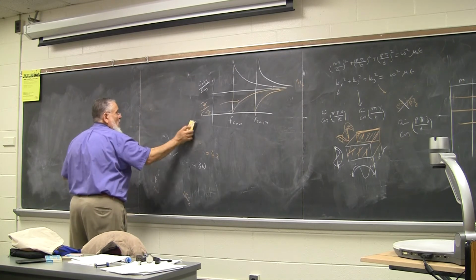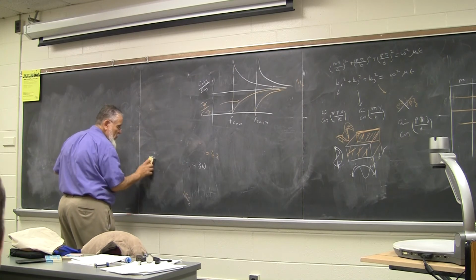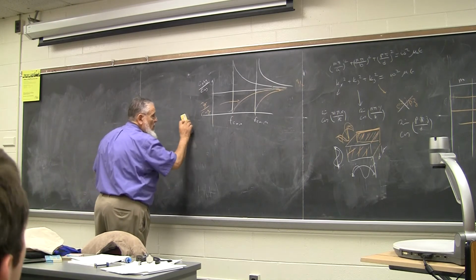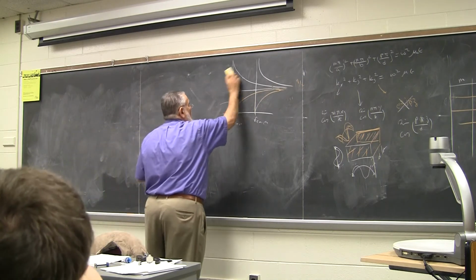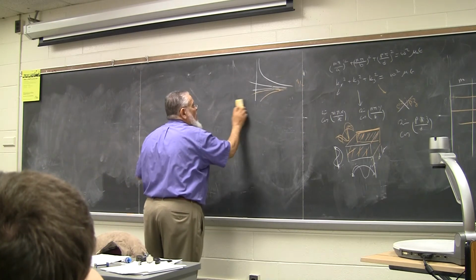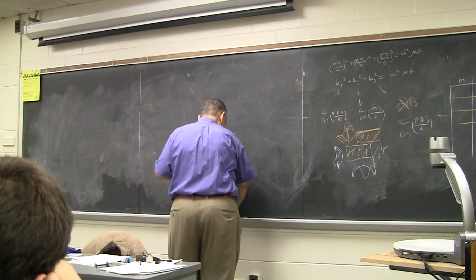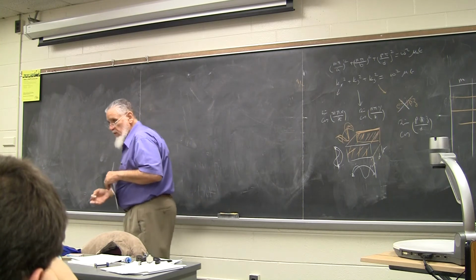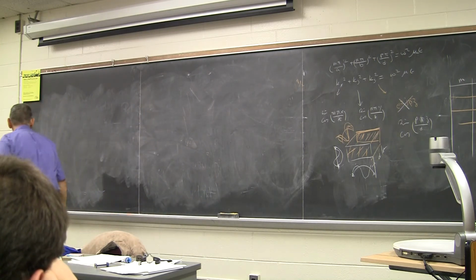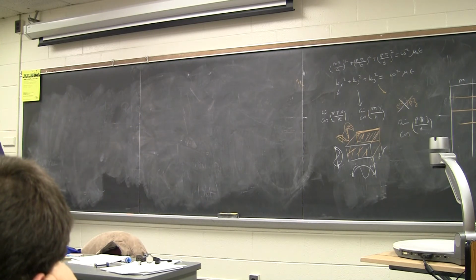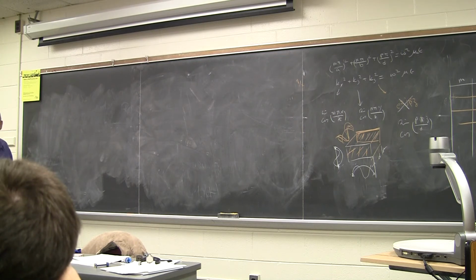Circular guides obviously are easier to machine and manufacture, and they have limited application compared to the rectangular guides. Like I said, if you want to do a resonator, a cavity, obviously circular guides are easier.